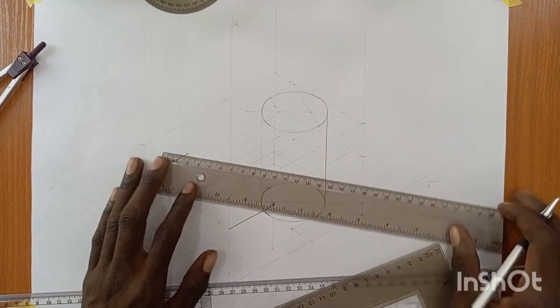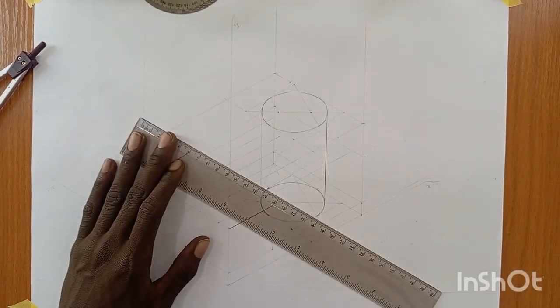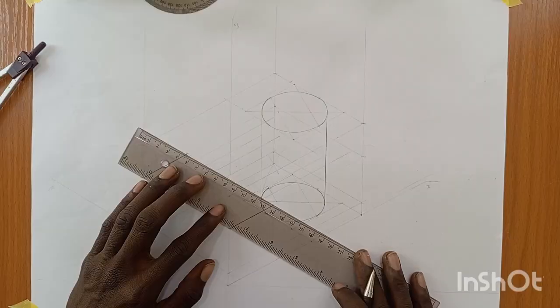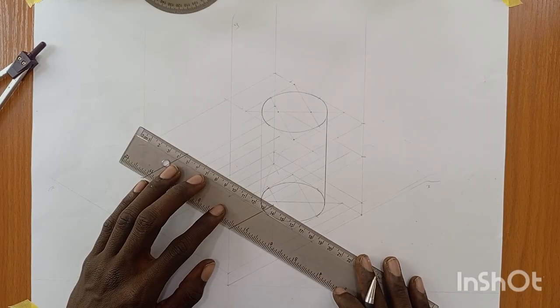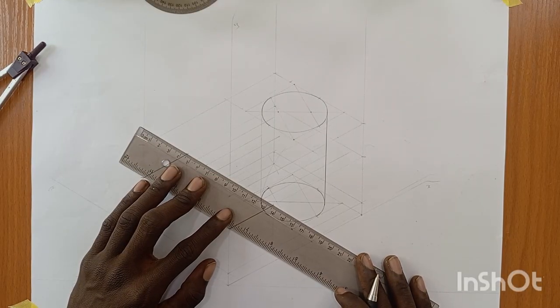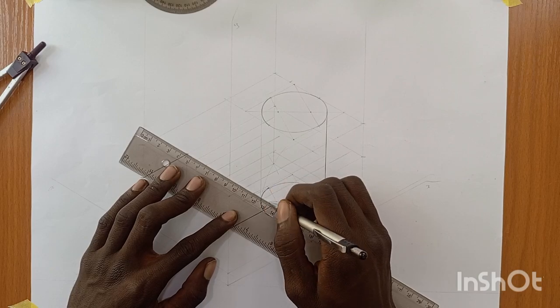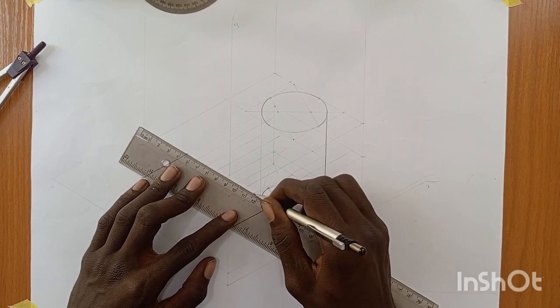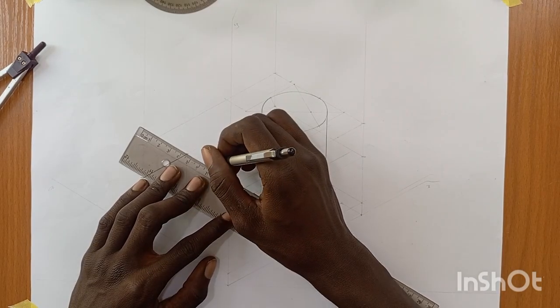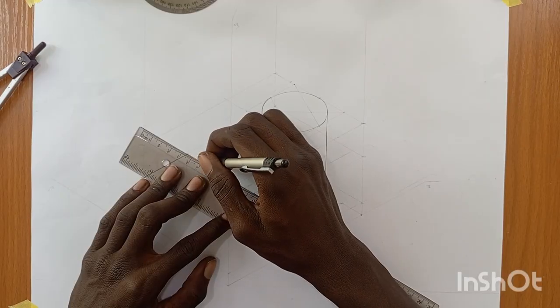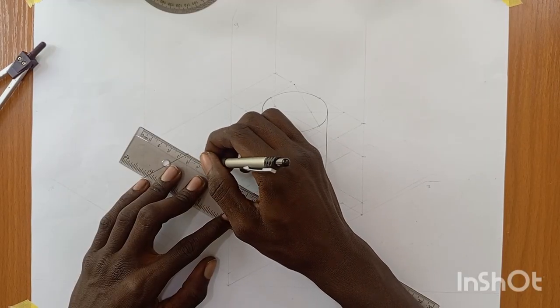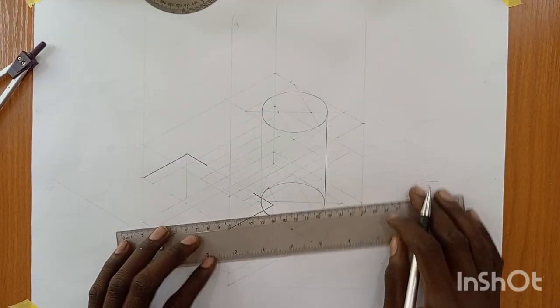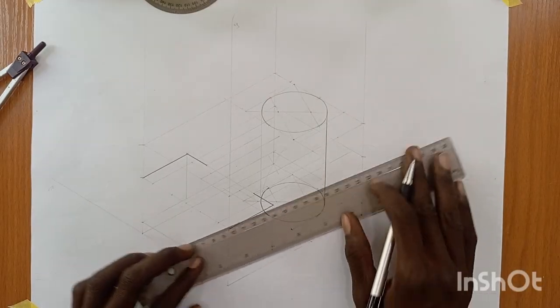Okay. I want you to draw your line, 20 here, maybe parallel. 20. If you've done it at least once, you will know which lines are going to be darker, which ones are going to be construction lines. So in the case of an exam, you can just draw those that are dark to make them darker, since you have already planned them. For the sake of the tutorial, we are following all the protocols to make the lines right.